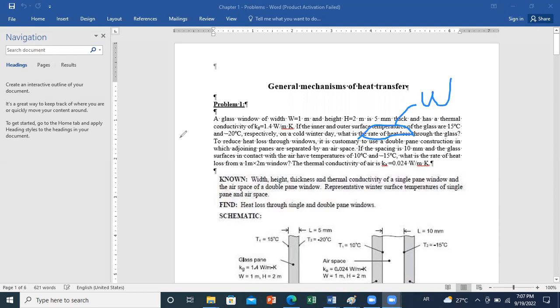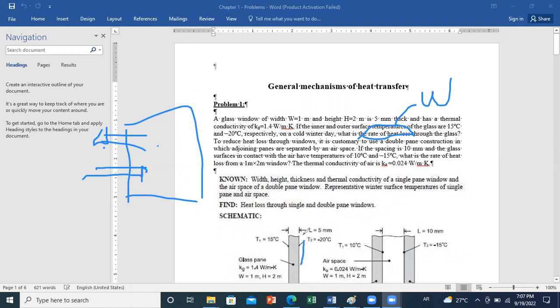You know that for a building, one of the big parts of losses is between indoor and outdoor spaces. In winter, heat will go from inside to outside, and in summer, we'll have heat from outer space to inner space. In both cases we don't desire this, because during winter we want to keep a high temperature inside, and during summer we don't want overheating inside. This is why we should carefully design the glazing.